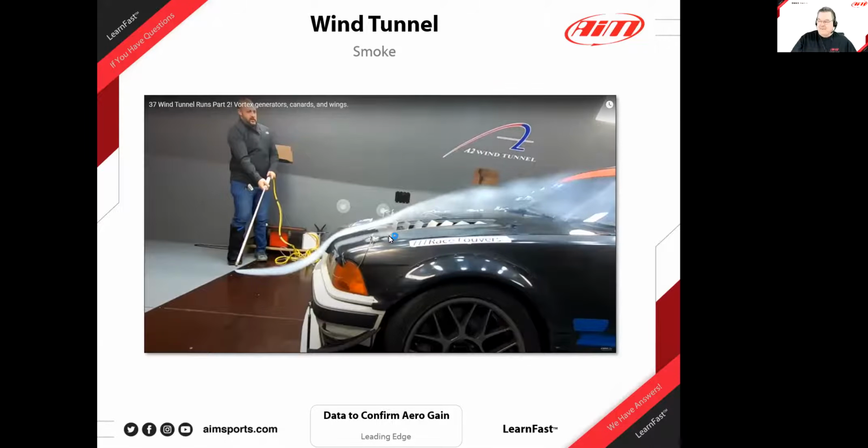Interesting. In most of our minds that don't understand this stuff fully, you've got these louvers you've plugged in here with about 1.5 inches, almost straight up for the first one, and they lay down a little bit more as they go, which creates this low pressure. When we first look at that, it's like this is a poor aerodynamic design, right? But in the end, it is pulling the hot air out, and it's even getting the wind to hit a little higher on the windshield. In the end, it's actually not so bad, and it's giving you these other benefits. So it's kind of a cool thing.